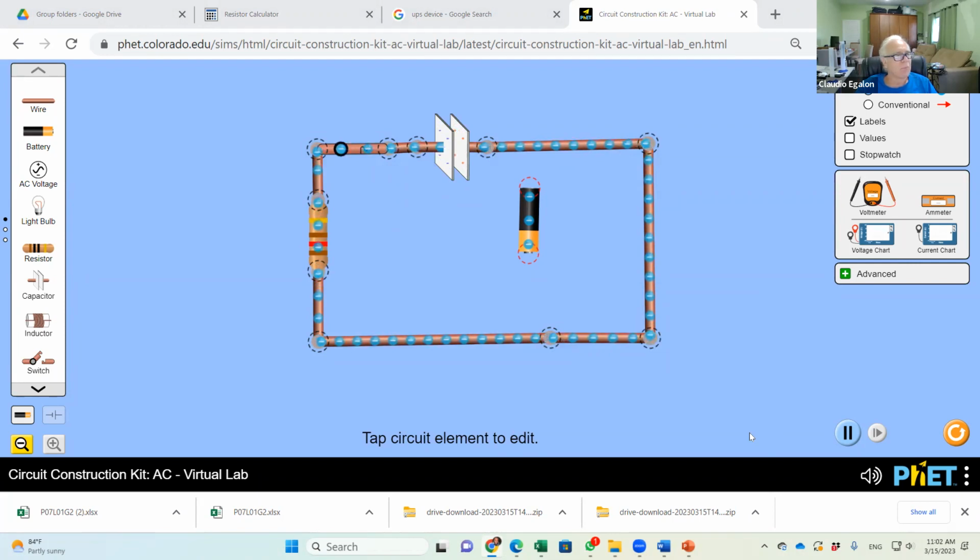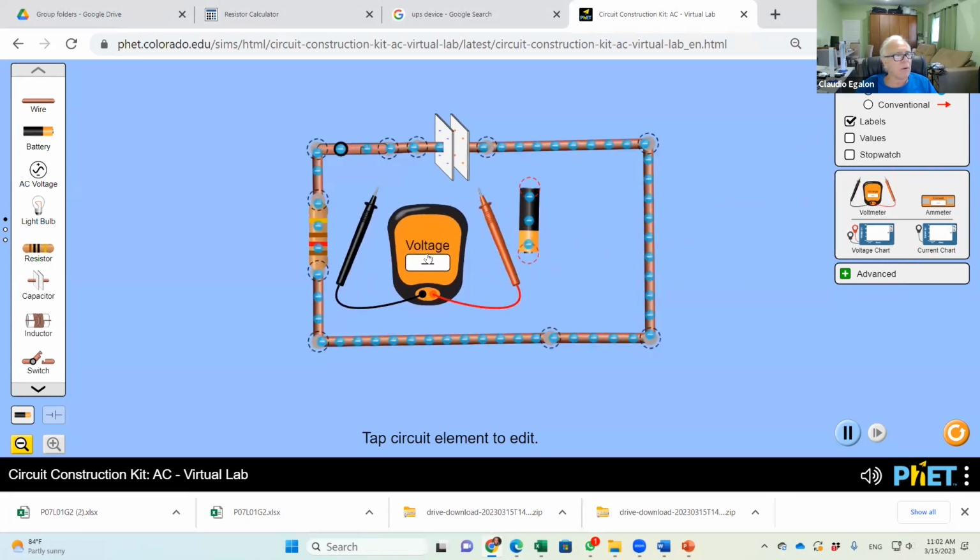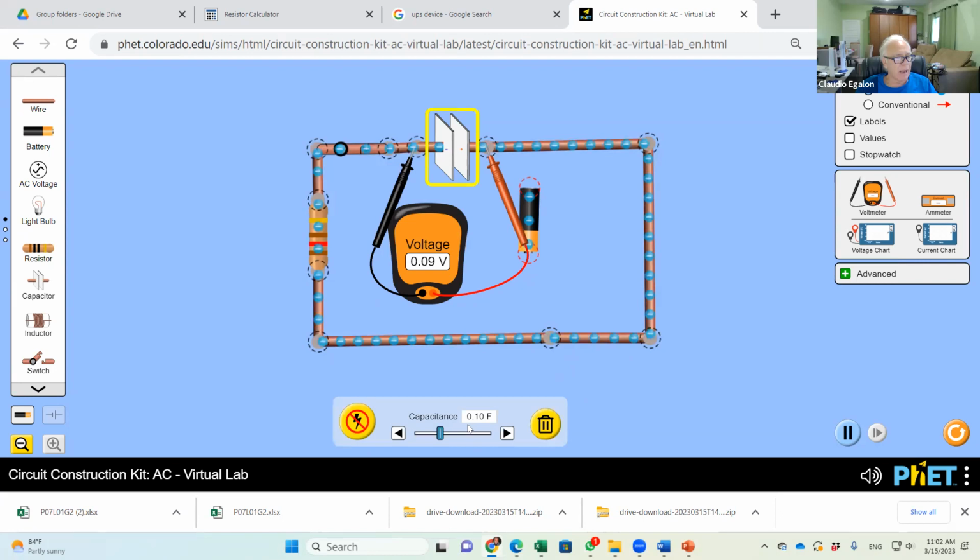Okay. And we can even connect my multimeter here to this capacitor to see its voltage decreasing, right? Or increasing. Yeah, we have 0.26 volts right now, and the voltage is decreasing. The voltage is decreasing because the amount of charge is decreasing as well. What's the capacitance of this capacitor? Oh, here you go. The capacitance of this capacitor is very high. It's 0.1 Farad.